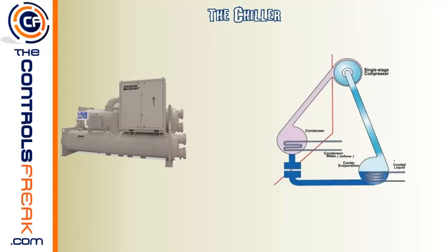One other thing to note about chillers is that in these barrels that you see here, there are many different bolts that come across here that seal up the 2 ends of this barrel. Inside the main portion of this barrel, these water lines that you see here are actually long tubes that run the full length of the barrels. So if you ever hear of somebody saying they were changing out tubes or they have dead tubes in the barrels, these are the tubes, and there are many of them.